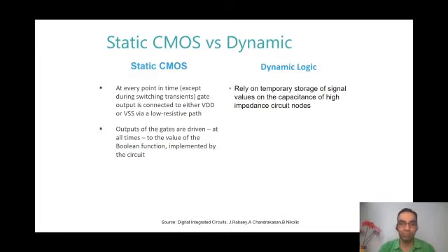But even in static, the voltage that he is observing on the output will transfer the logic to the other stage. In a static CMOS NAND gate, if there is some noise on one of the inputs, will the output change? Okay, the output may have a glitch, but it will again come back to the original correct state, is it not?